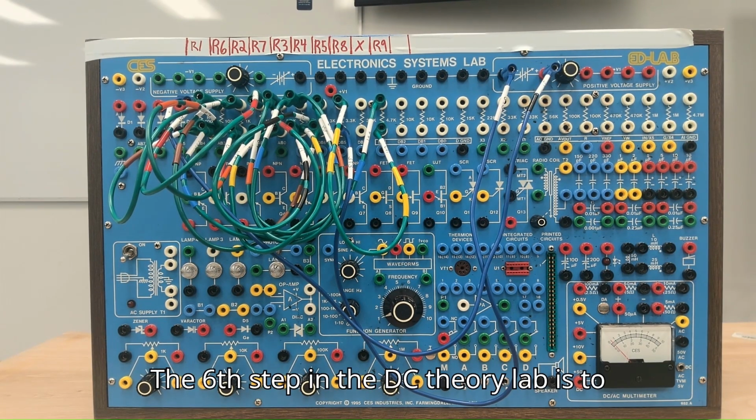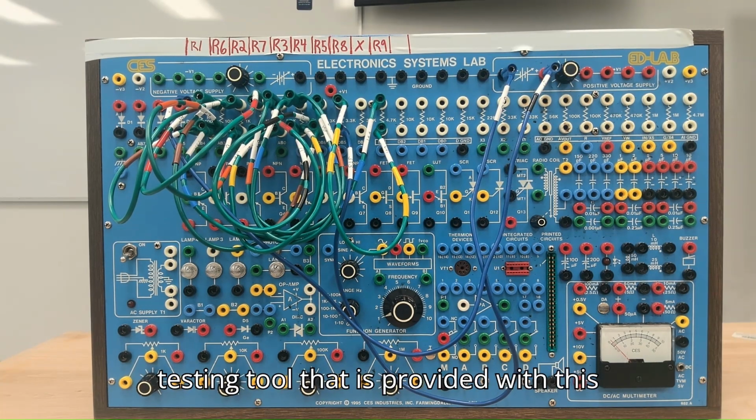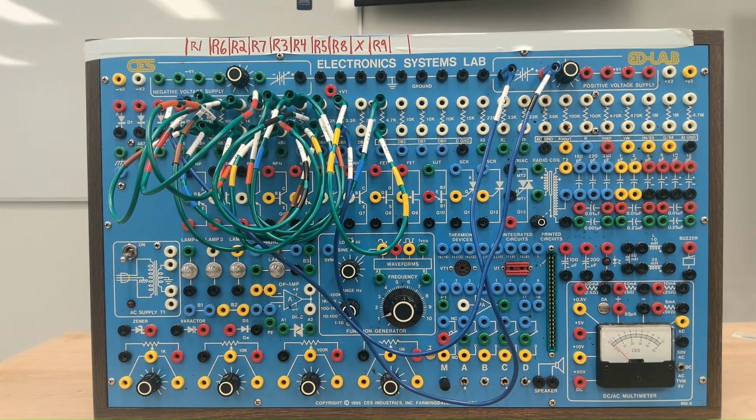The sixth step in the DC Theory Lab is to measure current within the circuit. The testing tool that is provided with this lab is a multimeter. This multimeter measures amperage by the inline method. Measuring total current and current throughout the circuit will require temporarily removing jumpers and placing the meter in line with the circuit. The first amperage reading we will read is the amps flowing through J1.